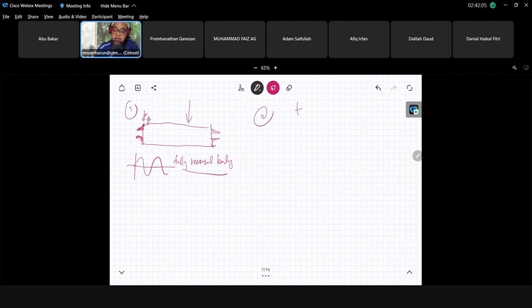The next question that we discussed today is different types of loading. So we have FR, radial forces, then tangential forces causing the torsion of the shaft, then we have axial forces. From here we have different types of stresses.